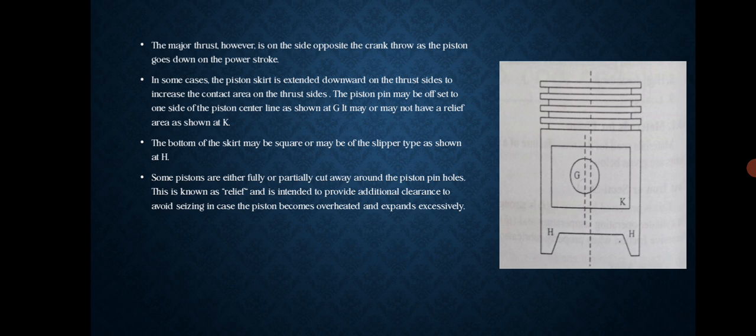This is known as relief and is intended to provide additional clearance to avoid seizing in case the piston becomes overheated and expands excessively.